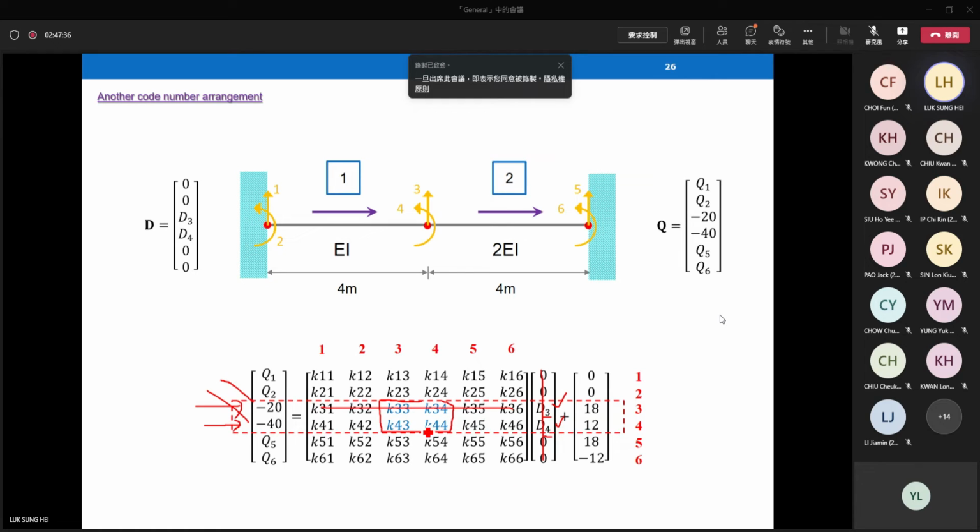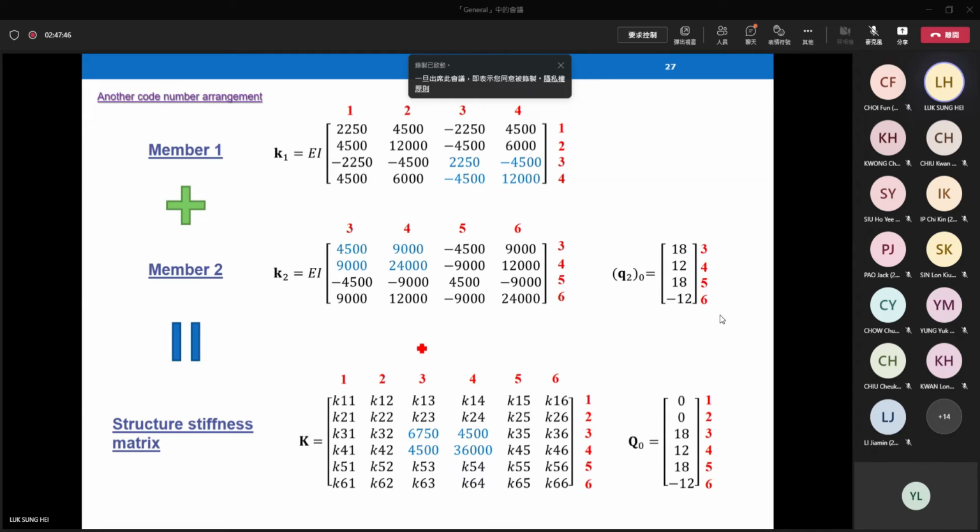So actually this is the so-called useful part, or you may call this K11 if you like. When you construct the problems, you can ignore the other useless part. You can ignore column 1, column 2, column 5, column 6 because it will not affect your calculations. Just consider the useful portion, especially the highlighted one in blue color.